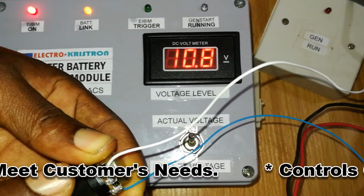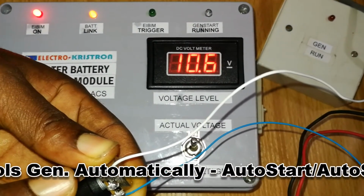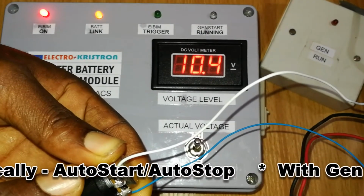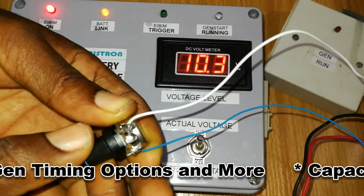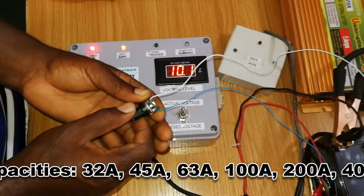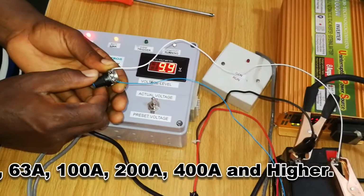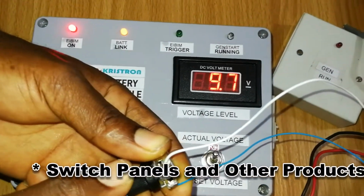Okay, you can see the voltage going down. Our target point is 6 volts. Keep going. We're expecting the gen run signal to come alive when the voltage gets to 6 volts or thereabouts.